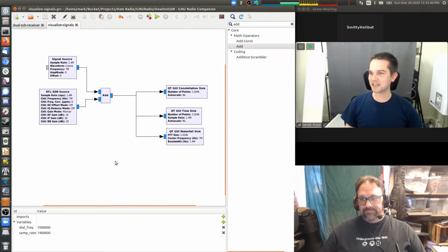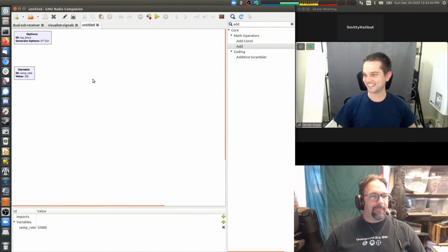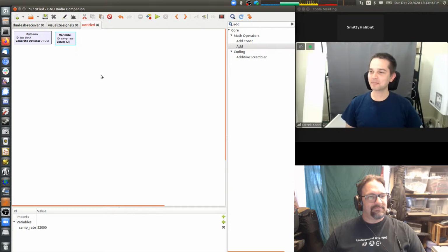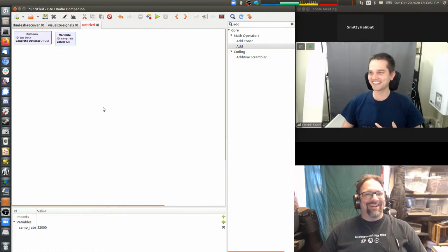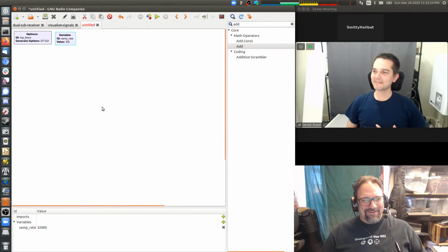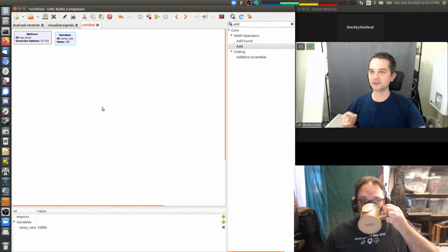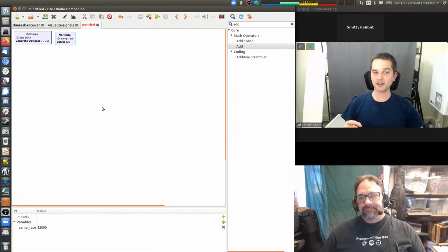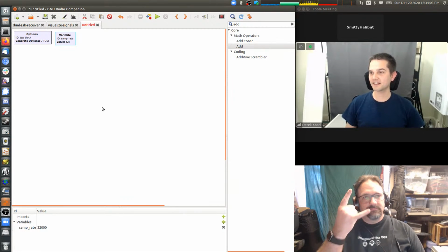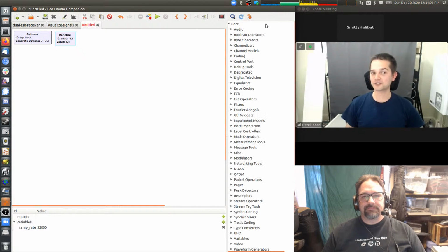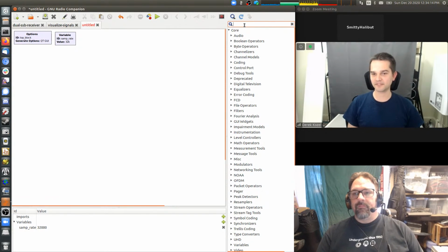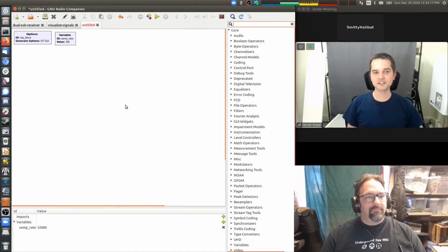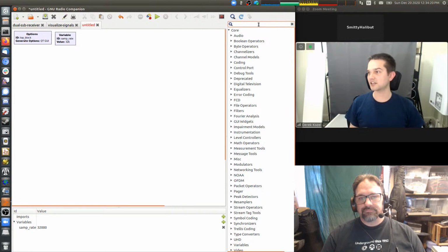So let's make a new flow graph, because I don't like the one you've got. Rule number 1, never look at anything on the air when you're trying to understand something. I could just remove the RTL if you need, but anyway. No, so what I actually want to do is create this flow graph using float signal sources, and then compose a complex signal out of that. Okay. So that we can start from things that hopefully are really more intuitive, and then build up to a more complicated setup. Perfect. So if you can drop in two signal sources.